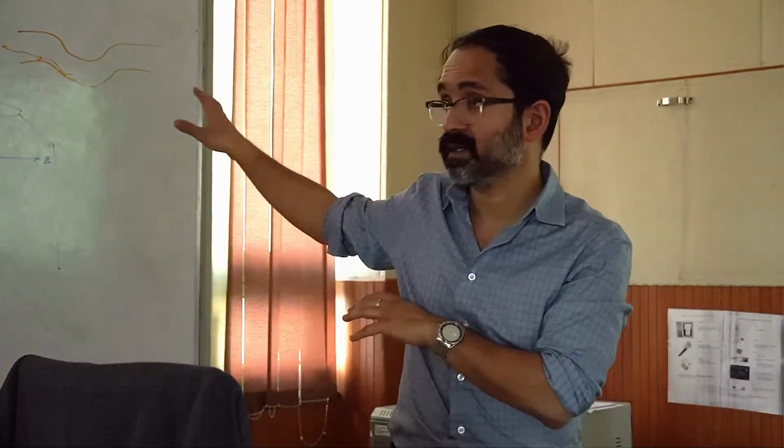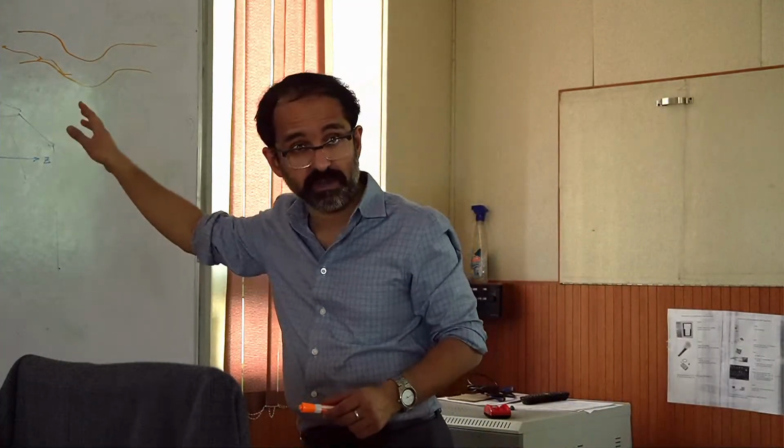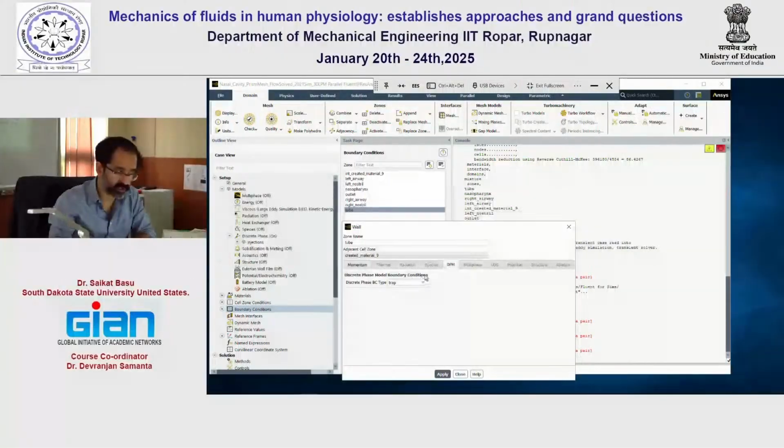Over here we have the sticky mucus that can trap the particles, but in other engineered systems we might not have that kind of hydrophilic nature to the surface. We did come across this once, and the experiments were being done at a different group, and the experimental data mismatched with our numerical results, and then we had to actually use the reflect condition and make sure that the wall conditions are accurately mimicked in the simulation. But since the mucus is sticky, we don't need to worry about that. This is a trap boundary condition even at the tube.